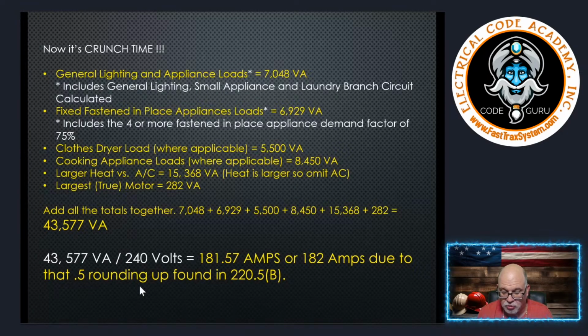43,577 divided by 240. That gives me 181.57 amps, 0.5 or greater. We're going to round this to 182. So that is the actual load that I need to make sure I have a conductor sized for. Okay, so I have 182 amps.